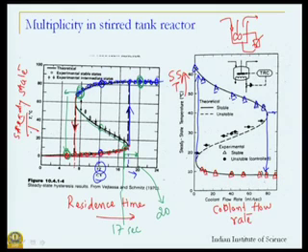Namely, for increasing the coolant flow rate, we get progressively reducing temperatures, but at higher levels of temperature, and at some point we suddenly see that temperature goes to a low value. It is again an exothermic reaction. So, you expect that low temperatures would mean very low reaction rates and therefore very little conversion.